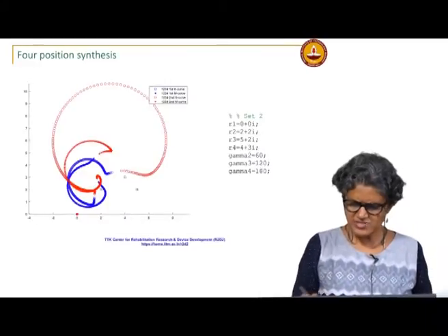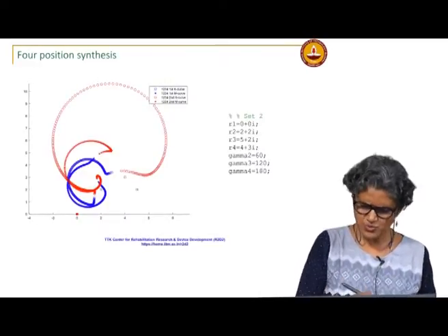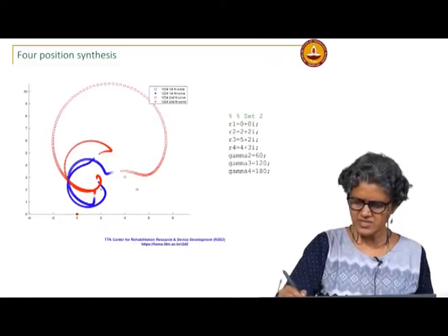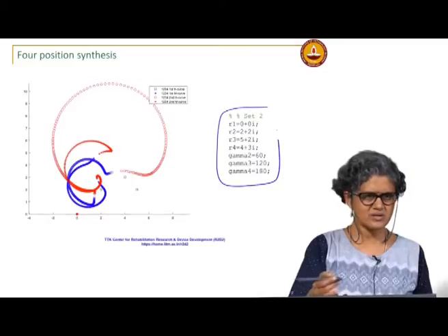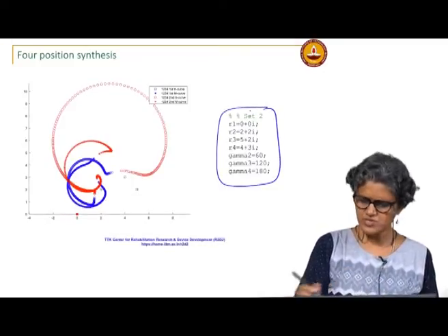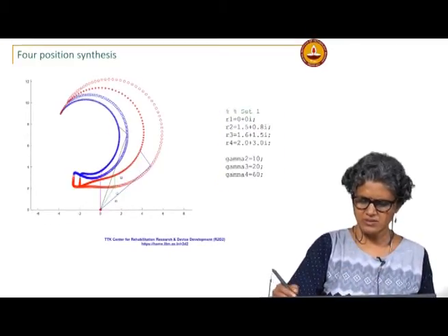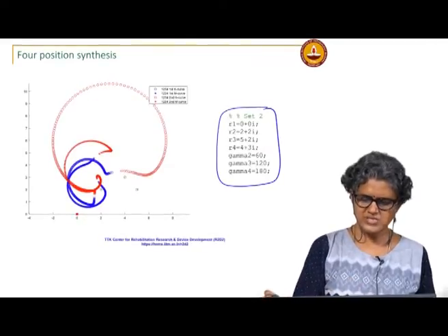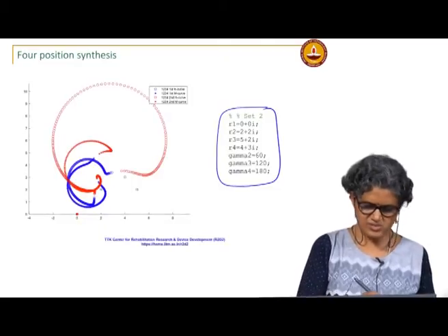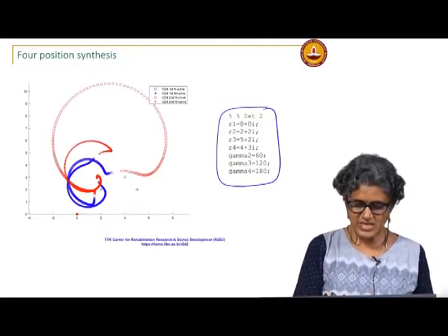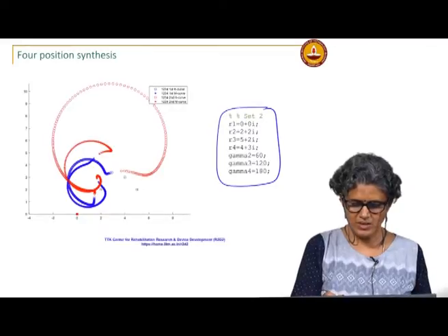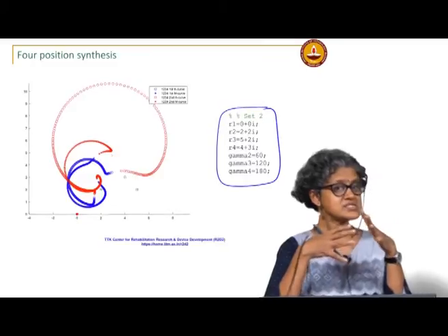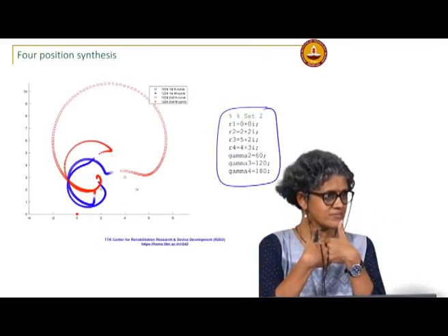There is a lot of mathematics in this. I have just plotted some. This is for some other set of conditions, so they can look very different. The first one was set 1 and this is for different precision points and rotations of the coupler plane. So, you can see here in this one they do not meet, which means the compatibility linkage does not close for certain positions.